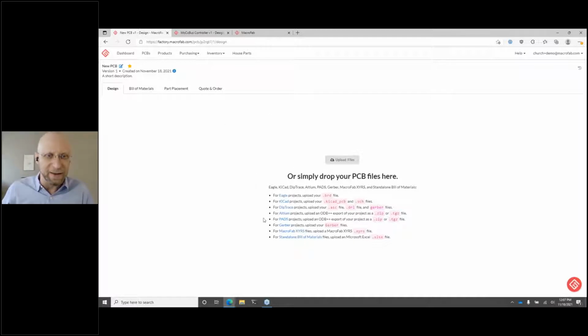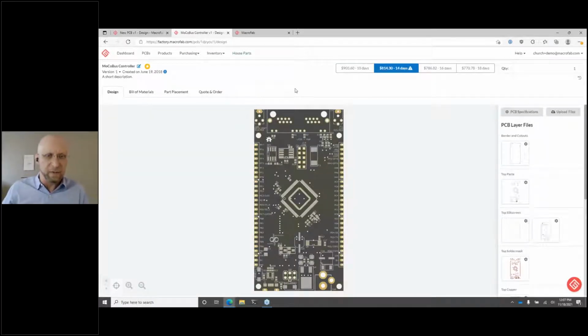So rather than getting started with a brand new project, I'm going to start out with one that's already designed so we can walk you through the different features and capabilities we have. In this case, this product was designed in Eagle or Fusion 360, whichever way you want to look at that. And in that case, I literally just dragged and dropped my board file in to get started. We were able to extract all of the placement data, the design, the specifications for the board, and the BOM as well. Additionally, under the bill of materials, I can literally just drag and drop an Excel file here and bring that in if I'm managing my bill of materials separately outside of my EDA tool.